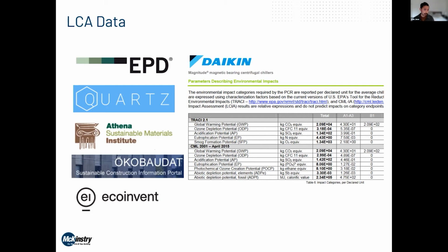And then if you don't have EPDs, you can use the A1 data from the raw material of the product. So if you are looking at steel, you can find the A1 for that, and then use the TM65 method, which I'll get into, to estimate your embodied carbon.